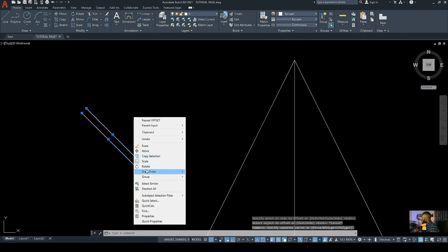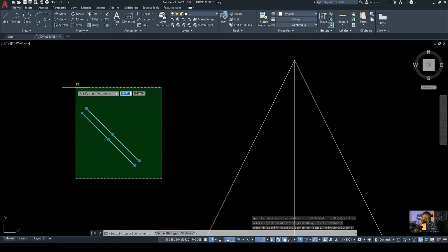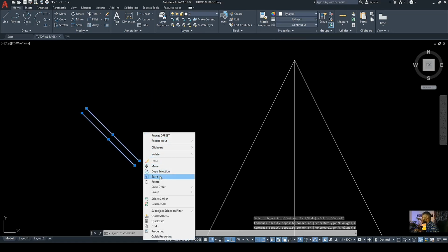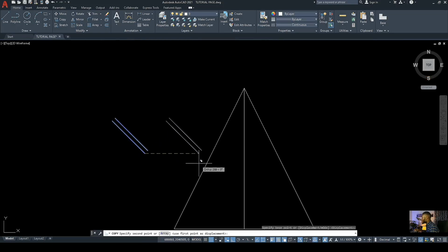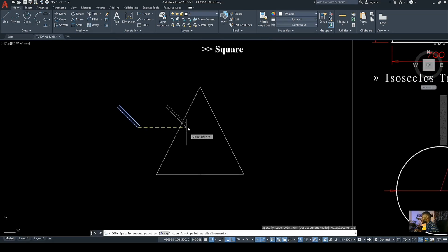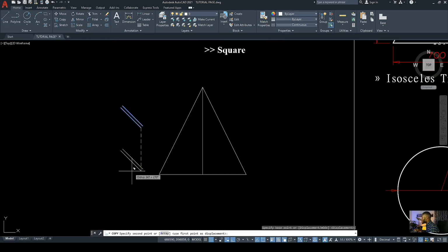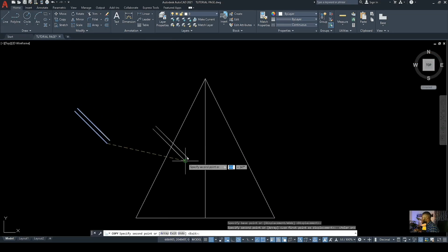So we can copy this by selecting, then right click, then you see your copy selected object, then you drag it to this point. You see, it's not even giving us the flexibility to bring it to the desired point because our restrict cursor orthogonal is still on. So it's just going horizontal and vertical. So let's uncheck it. Let's take it to restrict cursor to specified angle. So we do this. You see, we can adjust 360 to any point we want. So now we can bring this here and we just place it on the line here.